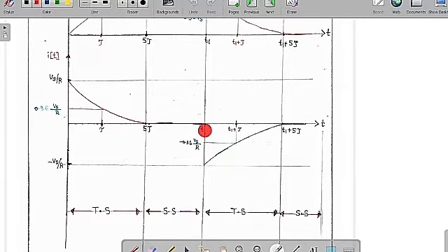After some time I move the switch to position B, so the current will be reversed. Then only we can say the capacitor is going to deliver the energy. So the expression will become minus Vs by R into e to the power of minus t by RC, and it is now going to decay. Therefore at 5 tau it is going to reach the 0 value.